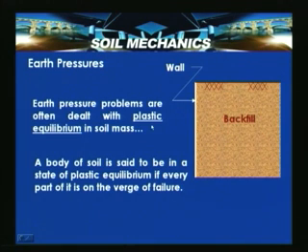These earth pressure problems are often dealt with using the plastic equilibrium condition in a soil mass. What is this plastic equilibrium? A body of soil is said to be in a state of plastic equilibrium if every part of it is on the verge of failure.